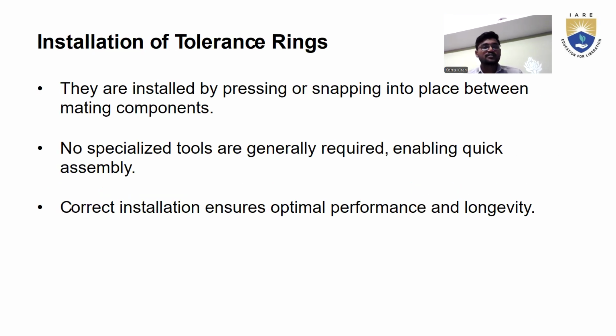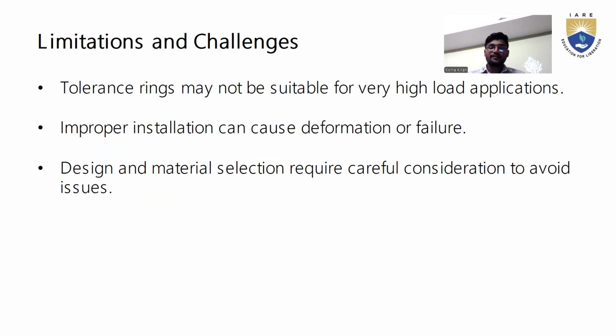Now, installation of tolerance ring. They are installed by pressing or snapping into place between the mating components. Yeah, exactly. And no specialized tools are generally required, enabling quick assembly. That is also one of the installation points. Also, correct installation ensures optimal performance and longevity.